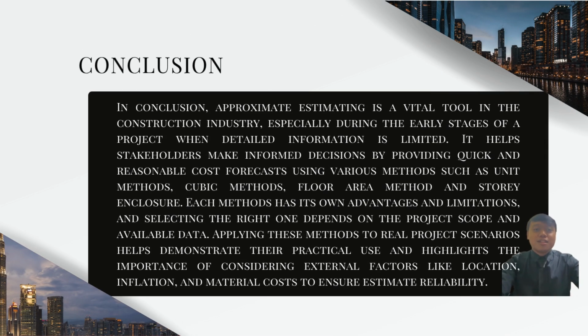In conclusion, approximate estimating is a vital tool in the construction industry, especially during the early stages of a project when detailed information is limited. It helps stakeholders make informed decisions by providing quick and reasonable cost forecasts using various methods such as unit method, cubic method, floor area method, and storey enclosure.